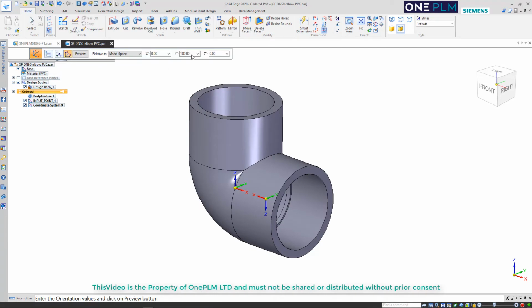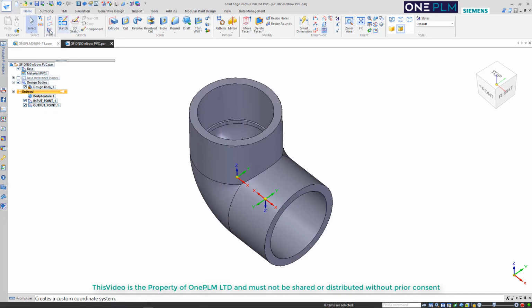So we actually just need to go back to here and make sure that we've got these orientations correct. So currently, let's just set that one to 0. So that one's correct. That one's still incorrect. So we need the Z going in the opposite direction in there. So now we've got 180, 180. We've got the X coming in the opposite direction. So that is now good for output point underscore 1. And when we're doing any of these names, we can't have any gaps. We have to use an underscore if we want to use these.